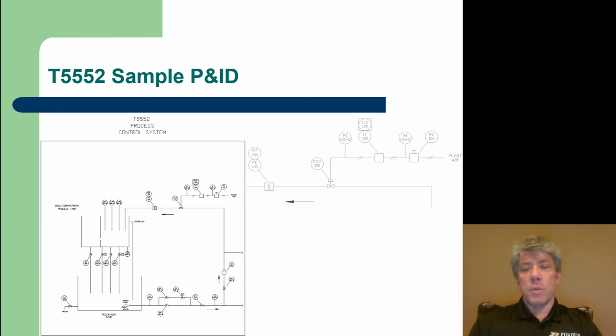In piping and instrumentation diagrams, those numbers would often have not just a 100 in them, but a 1 and then some other numbers. But generally the 1 indicates that they're all in the same area of the plant. They all work together somehow. Of course, there's exceptions to this, but generally I'd expect to find all the 100 series in one area of the plant and generally working together.